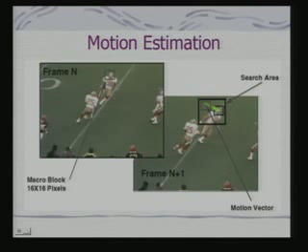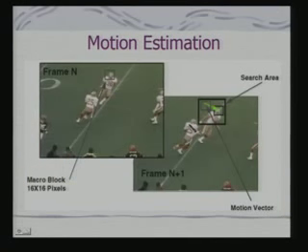and store the error corresponding to P frames. B frames mean bidirectional coding. In that case, it may be possible for me to predict a window here from one of the future frames. That means, from the frame n plus 2, I can predict also backward.